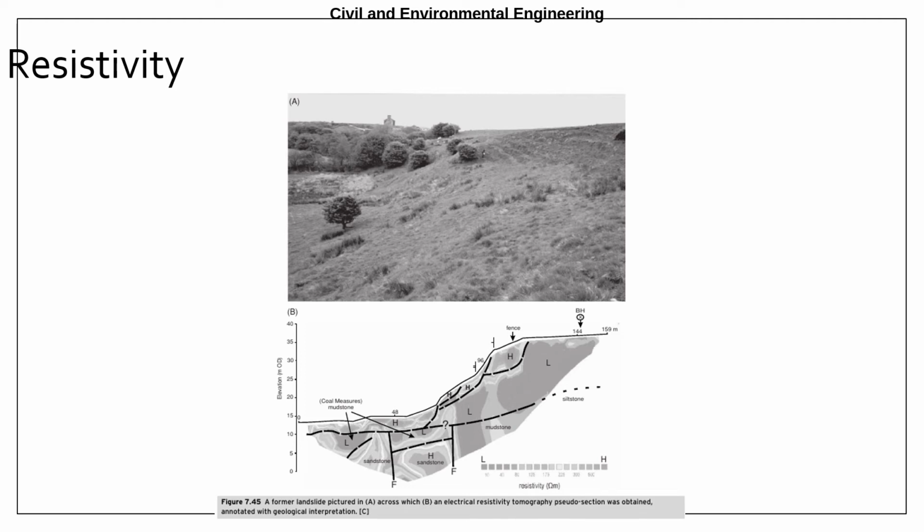So anyway, in this case, the landslide here is controlled by groundwater. The landslide is being destabilized by high groundwater levels, and the result is they are registering here as low resistivity areas. And this is more or less your landslide here.